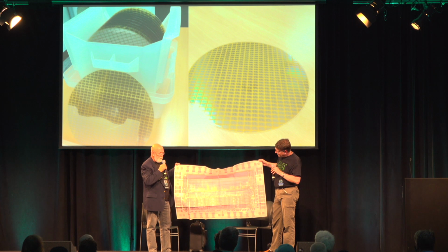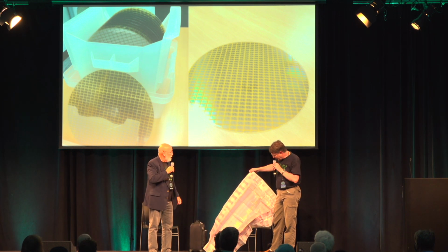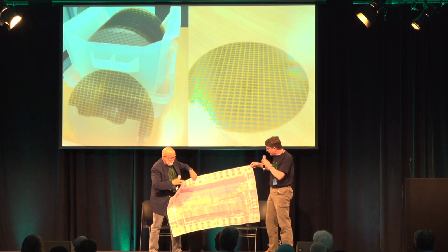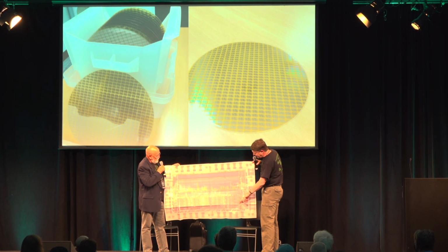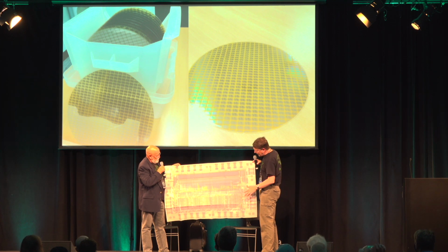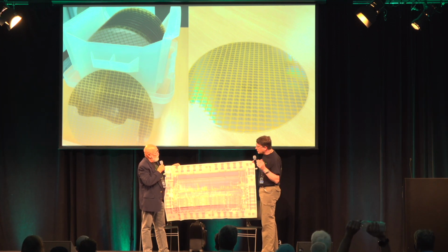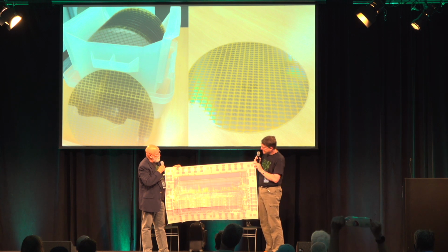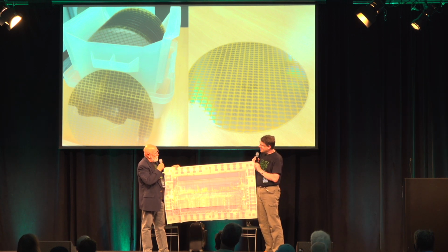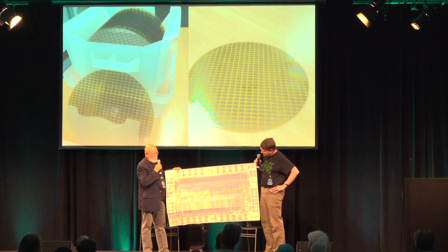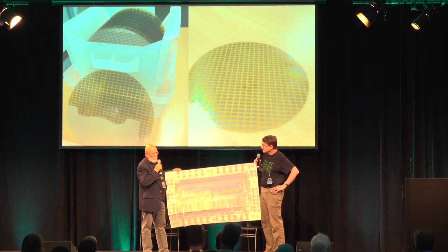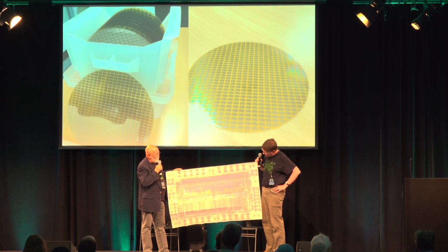One of the things I wanted to ask you about: we've got the same rough layout, with the instruction decode at the top and the data path at the bottom. The data path looks like an 8-bit data path. I'm seeing 8 channels. What's going on there? It is 8 channels, and for 16-bit, I put them side by side. Ah, okay. So look-ahead carry for the program counter. I only have an increment. I own a 16-bit program counter, but I can make a 24-bit address out of the bank address. So I had 24-bit addressing.